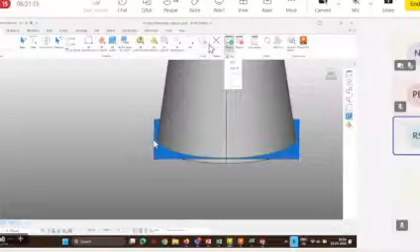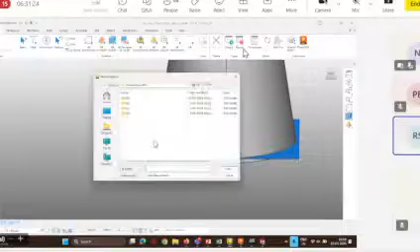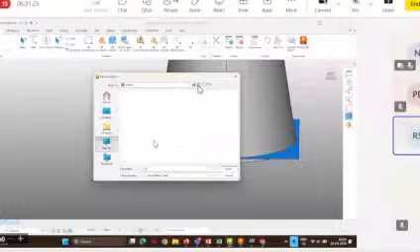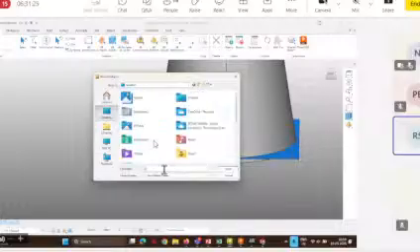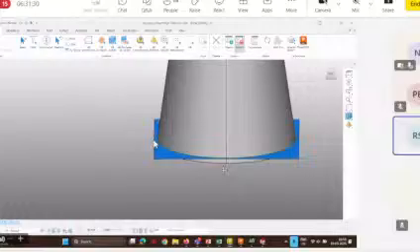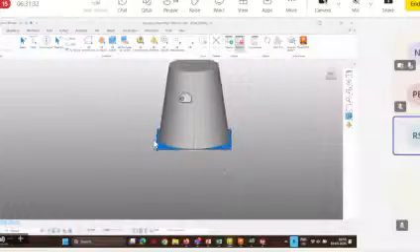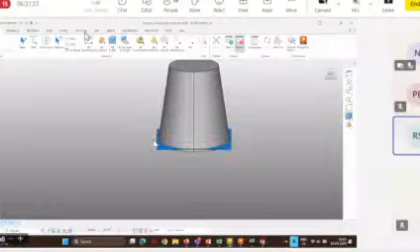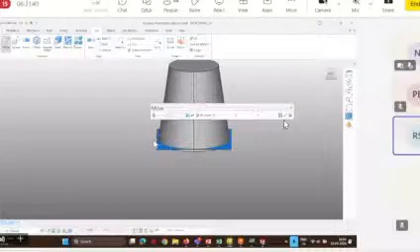So one way is we can directly start the macro recording. You can start from here. Go to the desktop maybe, and I will write maybe one and save. Now whatever I do now, those commands will be stored over there. So maybe I want to move it. I will select this one, edit, move, and maybe by Z height and click OK.